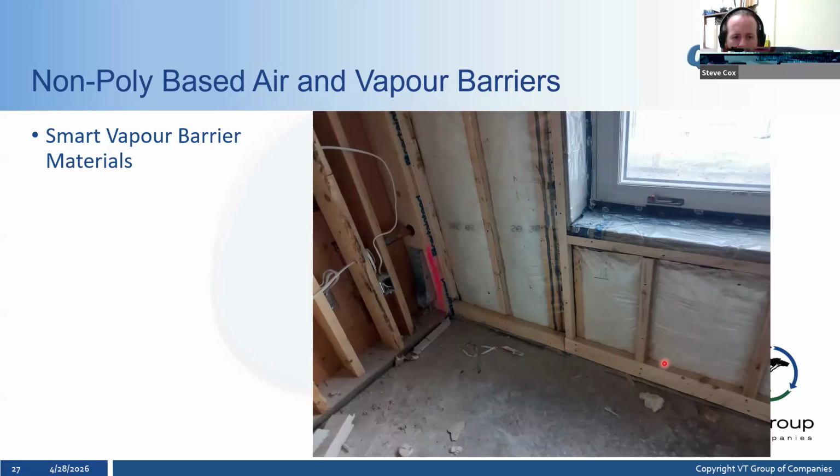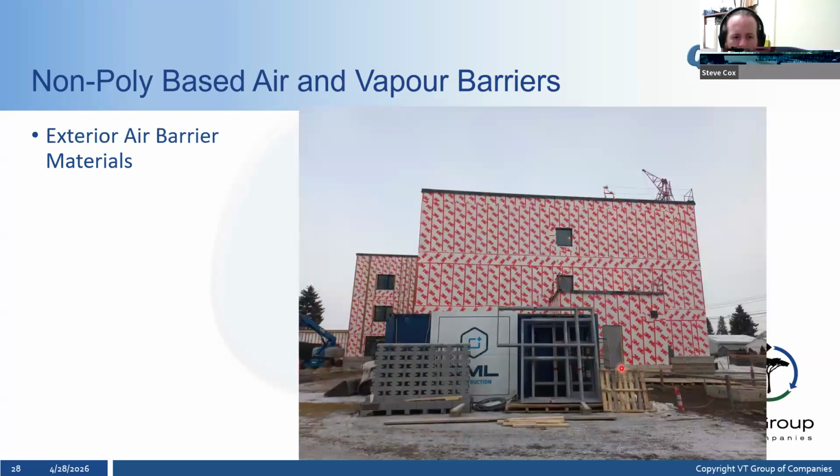This is a redundant air barrier layer. They've treated this interior as if it's the air barrier layer. They've compressed it everywhere because I have to do negative and positive pressure testing. This was a really good test. The primary air barrier layer on this one is the exterior. What they've done is a peel and stick material on this one, a 3M vapor permeable material on this one.